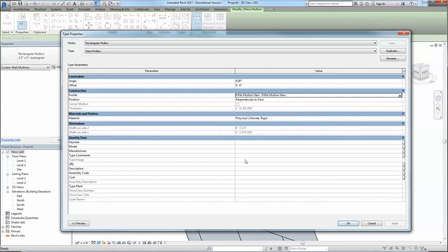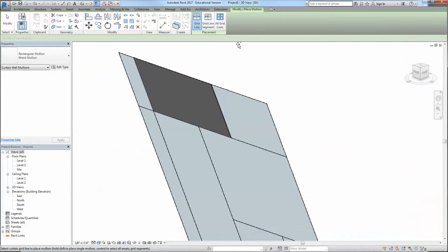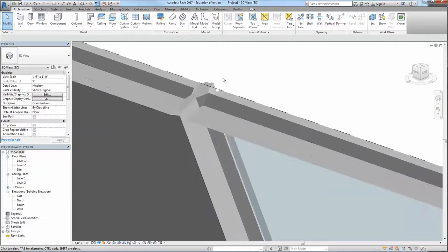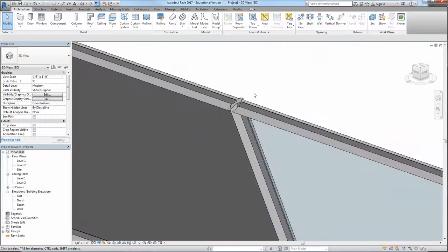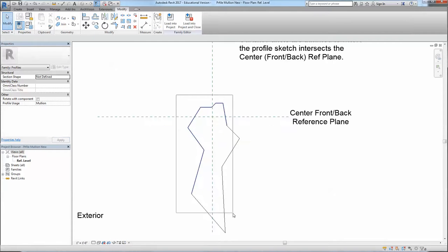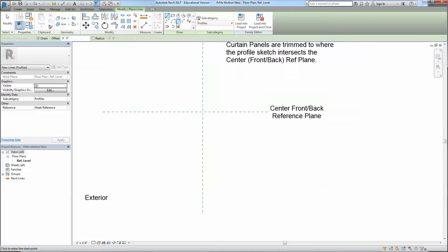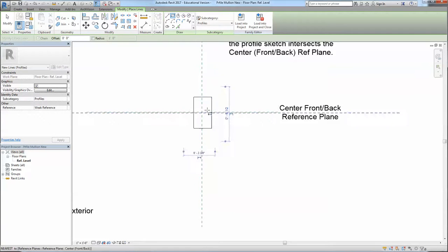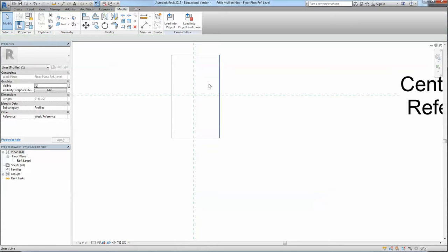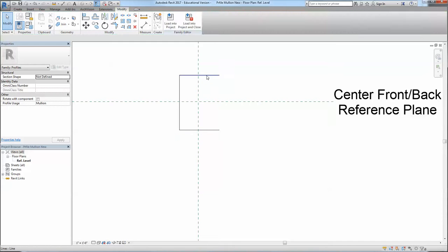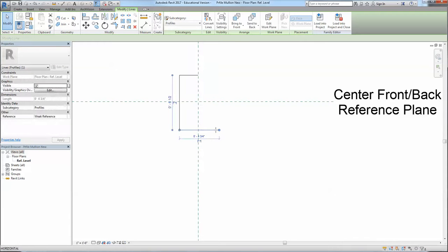Mullion new. Okay, so that means that this new mullion, the weird mullion, is going to have that profile assigned to it. I'm going to say all grids, and there you have the weird profile. So in that sense, you can obviously go back to this profile and make it a bit more logical, or something that is a bit constructible, no? So you can do a rectangle shape, make sure the dimensions are correct. You can do your mirroring, you can do your trim.